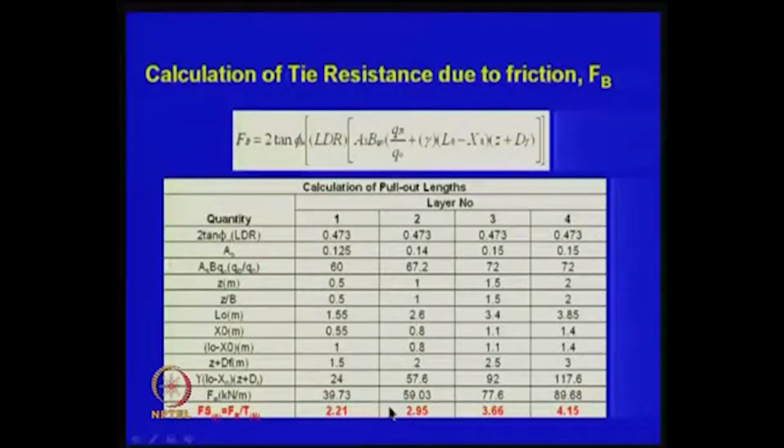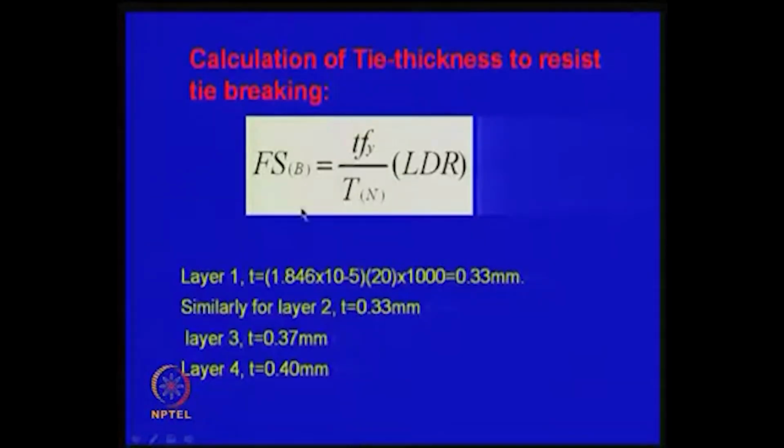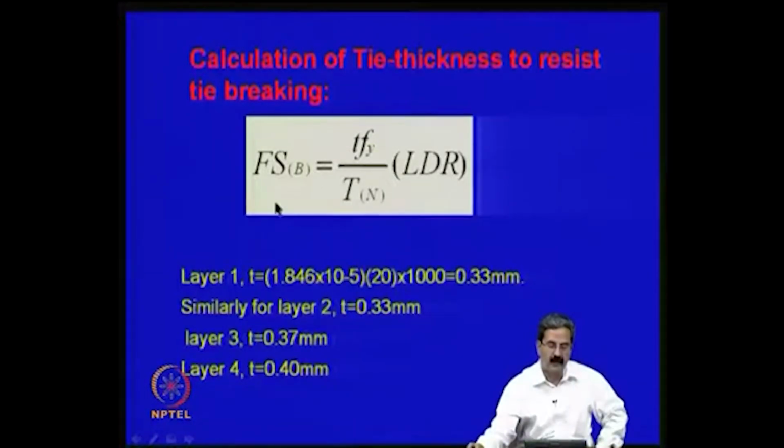So, you have to somewhat reduce it, anyhow we will see that, but you can increase the footing size, like say B equal to 2 meters or 1.5 meters and try to do some more modifications, that we will see later. But this gives a basic idea that you can calculate the tensile force required and also the pull out resistance and other factors. As I just mentioned, now we know what is the factor of safety required.